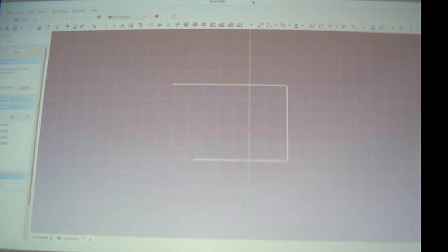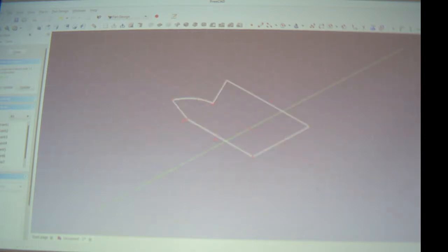And let's do an arc. A circle there. There we go. And I go up there. So let's say I want to make something looking like that. I don't care. But what you're going to see up here is it says this is way under-constrained. I don't know how wide, far, whatever everything is in here. So you've got to tell me some more about this world that you have.